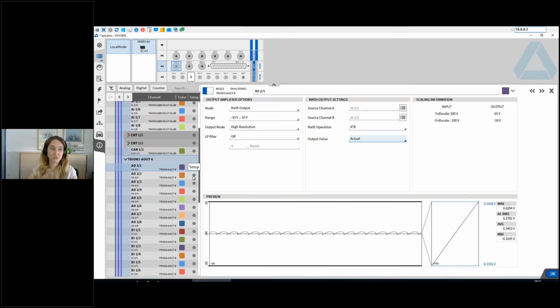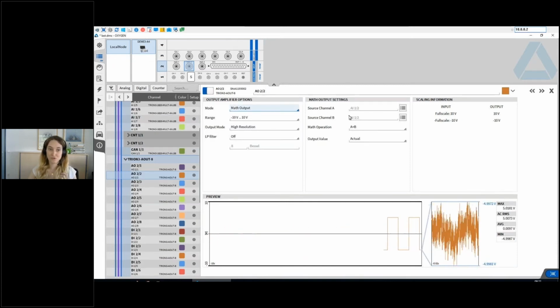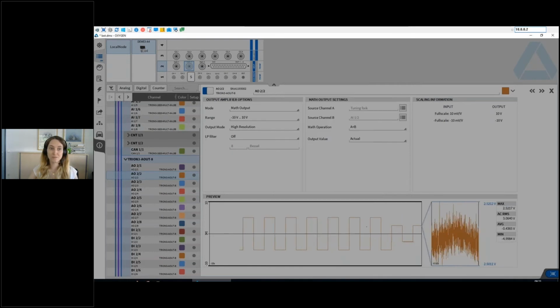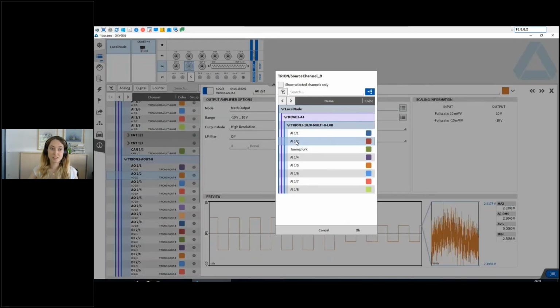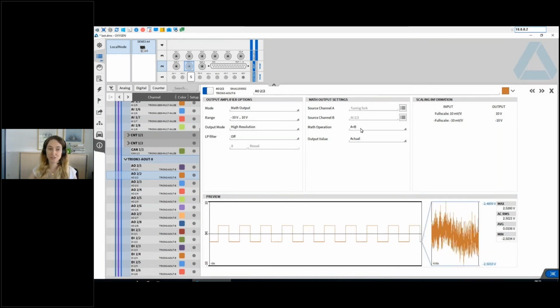As a second option, I can not only use the function generator here, but I will use the strain gauge, the tuning fork. So I will use the tuning fork as my first signal, and as the second signal, my rectangular waveform here, and add those two signals together. And as you can see, again, if I press the tuning fork together, the signal will be modulated here.